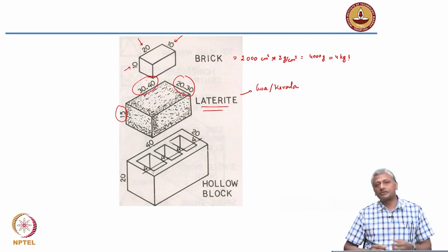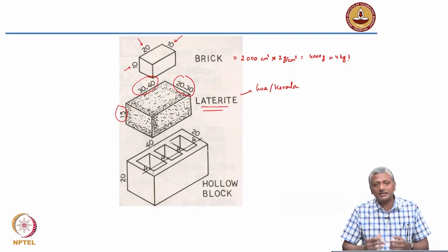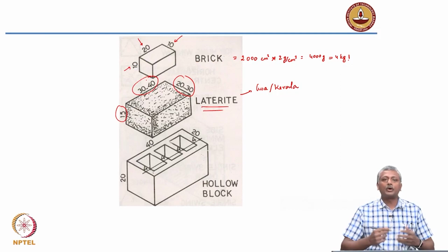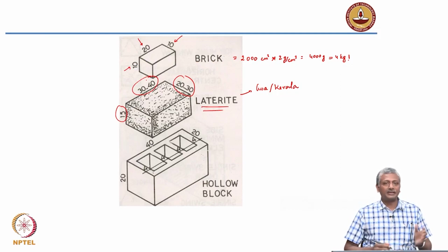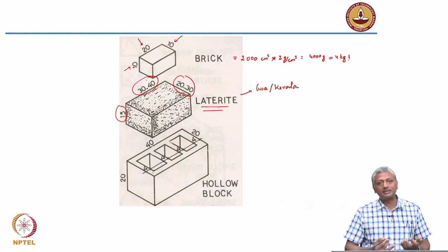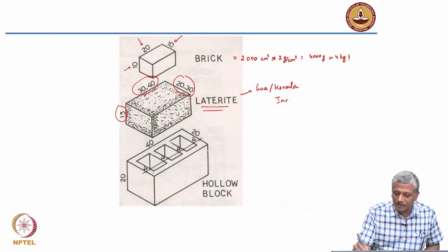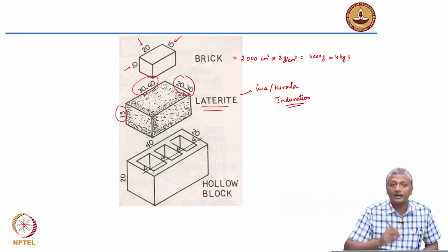It's a very different type of stone as compared to granite or limestone or quartzite, which are extracted from quarries, and those typically don't change their structure very much in the long term, except when they are getting weathered, and that's when adverse reactions actually happen. With laterite, on exposure to a benign atmosphere, they will slowly gain strength and indurate. The process is called induration. The slow strength gain with age of laterite blocks is known as induration.